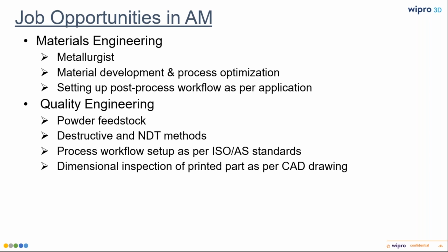The team should be in complete understanding. And once the part is printed, we would want to carry out the dimensional inspection, whether it's within the tolerances that the customer requires. This can be done using the CMM setup or the scanning setup. So again, to drive home the point, 3D printing alone will not be able to take care of all of these things. It's going to be in accordance with what is available in conventional and traditional manufacturing.